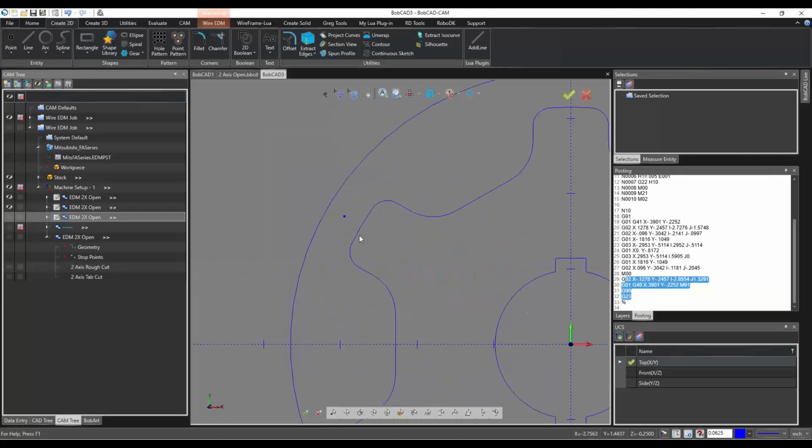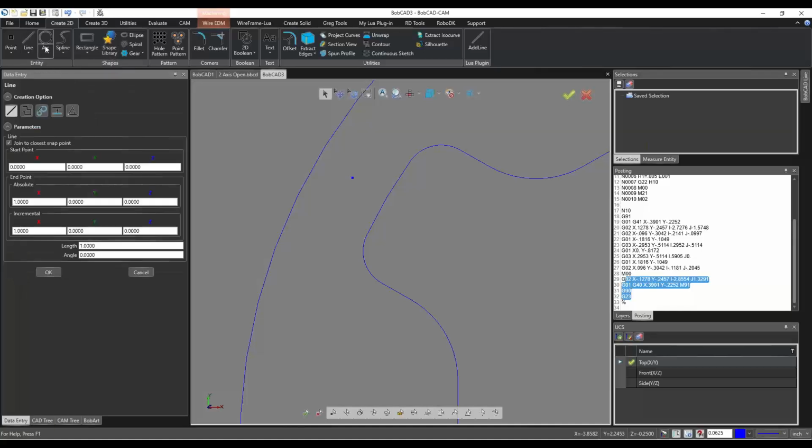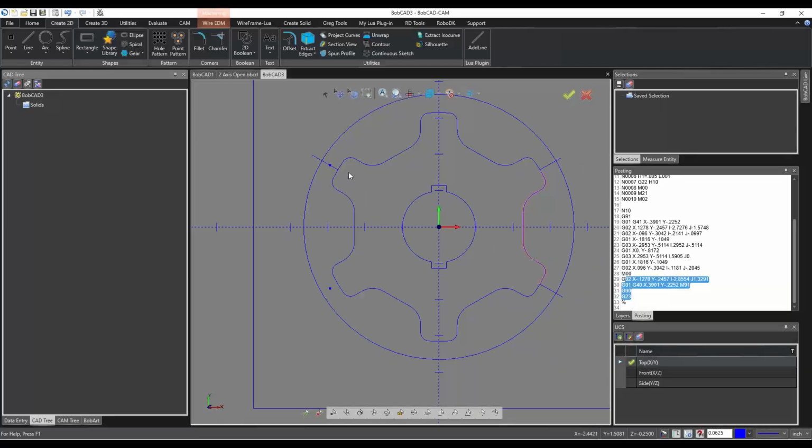And after that, we also showed how to create these points right here. And what we did was we went to line. We just kept it to the default line. We didn't try any of these other ones, but by the way, you can. We just kept it to the default one. We selected the midpoint of the geometry. You hover your mouse over this arc to grab this construction geometry line, just like that, to snap it. Then we trimmed away that bit and put the point right in the center. And that's how we got most of our CAD stuff.